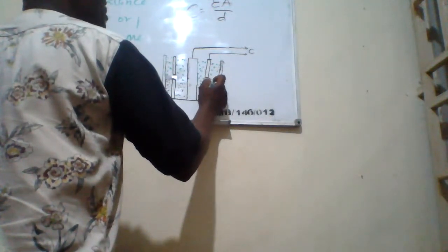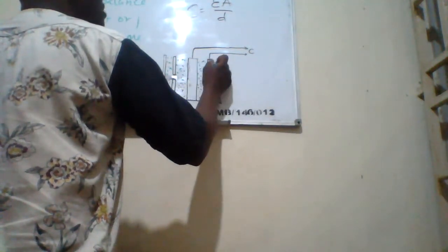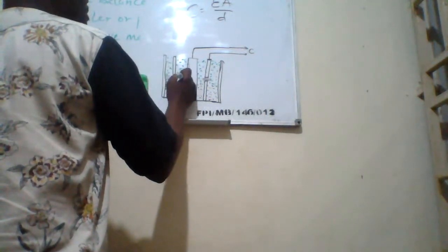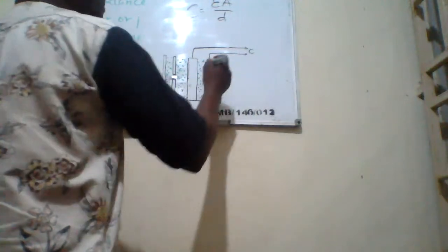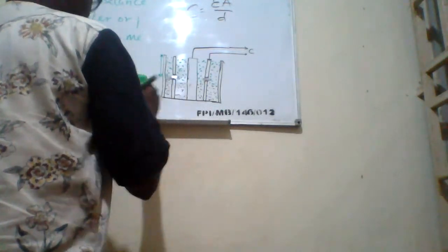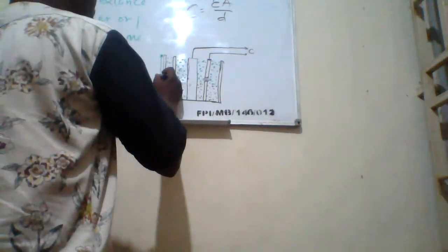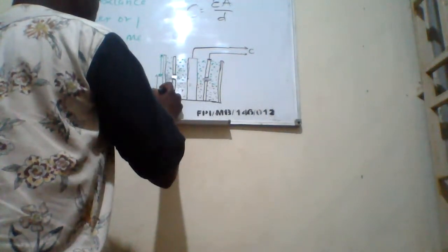For that reason, there's going to be two capacitances formed. One capacitance will be for the portion of air, the height of the air, and then the other one will be for the portion of the fluid in the tank. We have the fluid at this level.